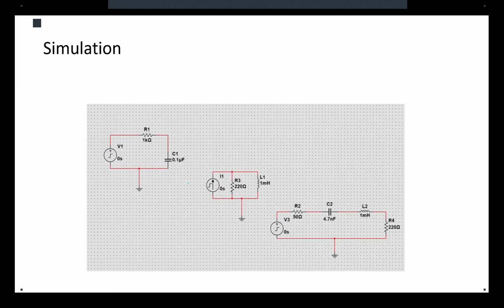If you run those placements, you are going to see you have to create such a circuit. This is RC, you just put in the components, the source, R, and C. Double click on the source and put the initial condition as 0, all of them. Okay? Because we want to start from 0.